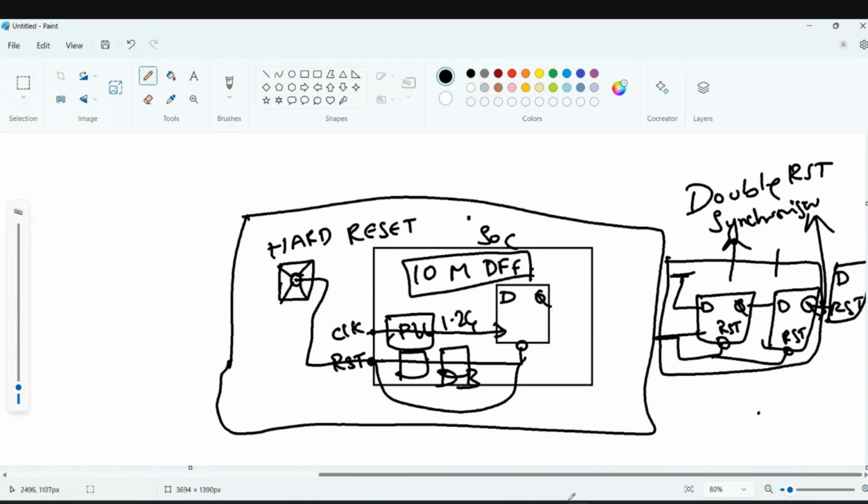In general, in all the internal circuits, we always use a synchronous reset. For DFT, we prefer using asynchronous reset. Again, that is a different case. Synchronous reset is not controllable, I mean, controllable in the sense that you need to add a cut point here for DFT. Again, we will not go into the DFT concept. Currently we are going through digital electronics, so we are in the RTL perception.